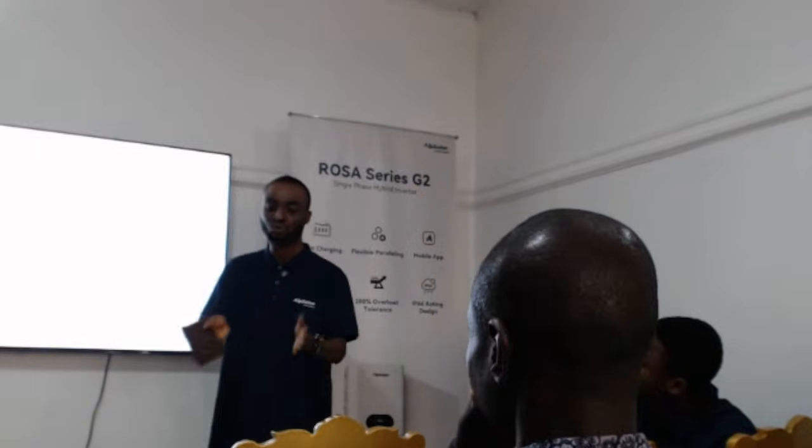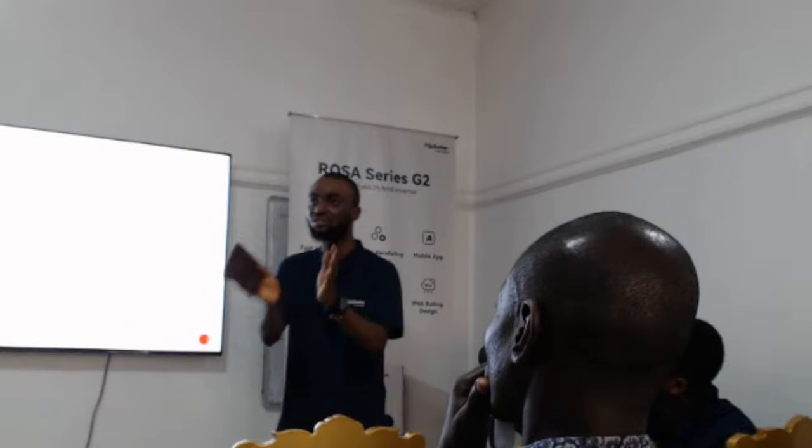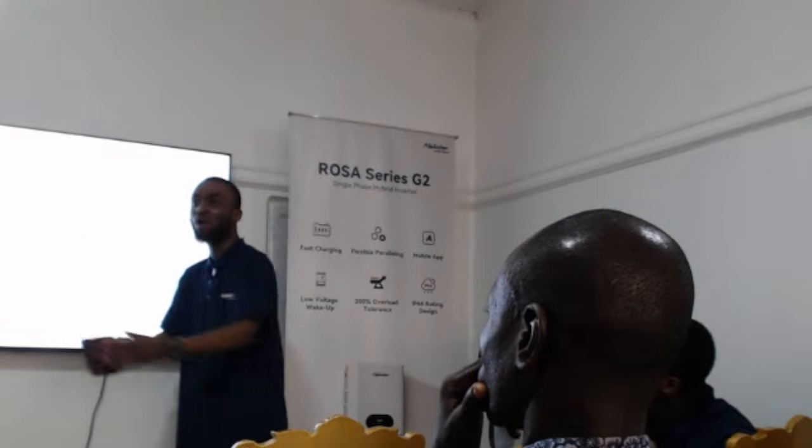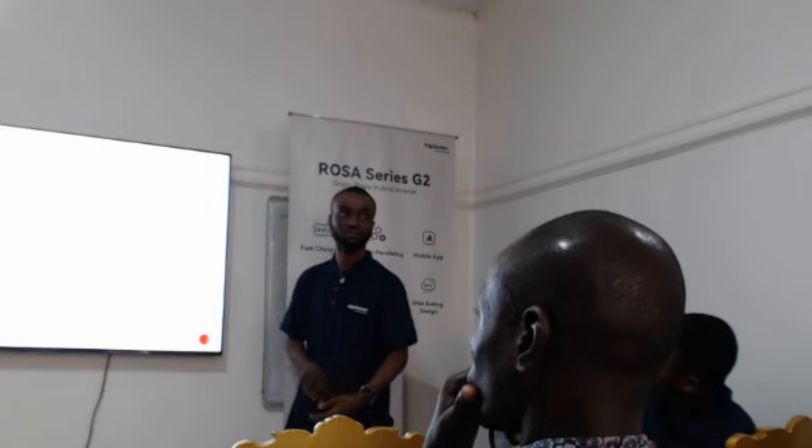But you said we should go and set the slave address on the slave. No, that is to connect them together. What you are setting is to put them together as a unit. So you set the parameter for parallel on the master, and you set the parameter for parallel on the slave. But any parameters that have to do with how they will function, like the energy mode and all this, go across to all of them. Just those slave addresses are not.